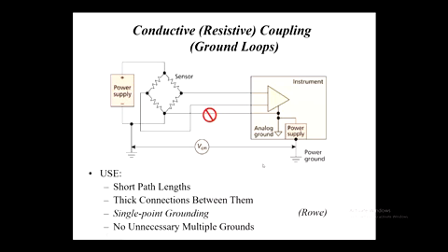Inadvertently, we might have a tram going past out in Royal Parade that creates some ground current in its powering, and it just happens to drag current through between those two points. Through that finite but very small resistance, if there's a large current through that, that will produce a voltage.